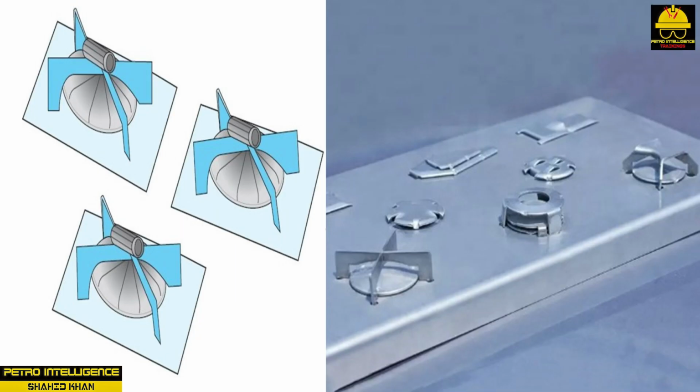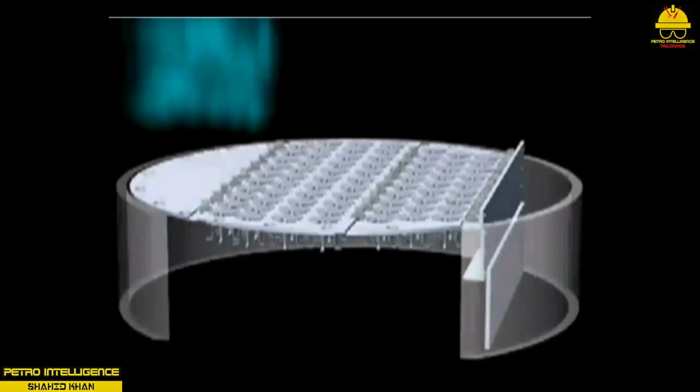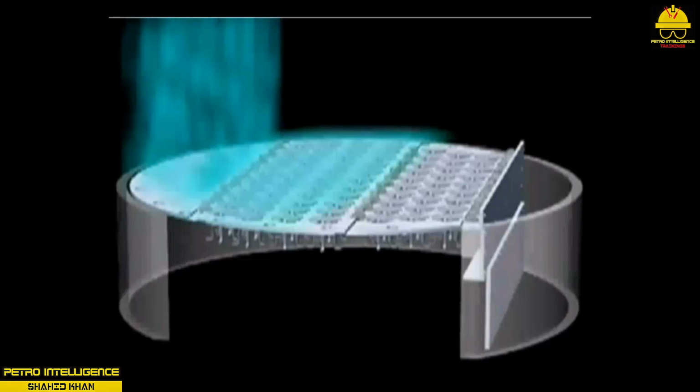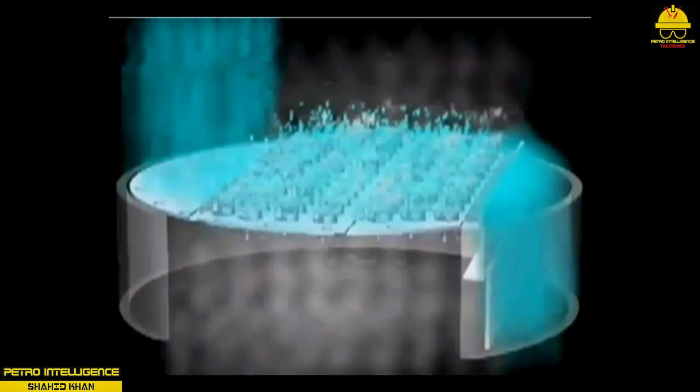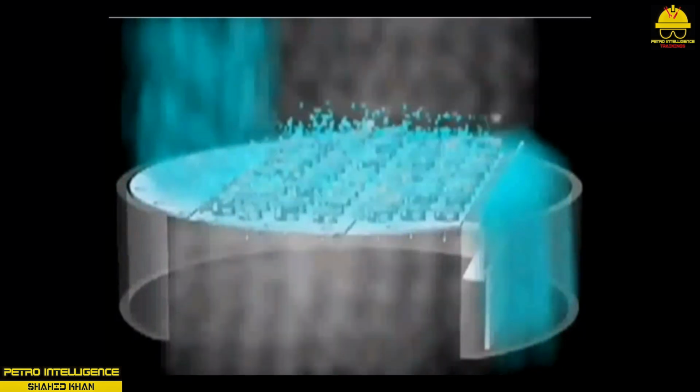Valve trays, as shown in the picture, have simple, movable plates. Plate movement depends on process flow. This type of tray is more efficient over a wider range of flow rates than the sieve tray. Each valve is a metal strip or a small metal disc that lifts under vapor pressure. Flow is directed horizontally on the tray to produce good mixing.